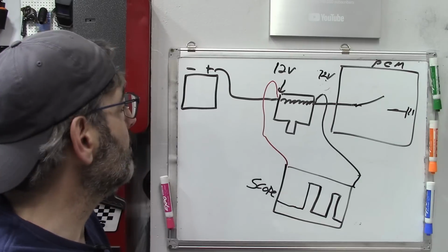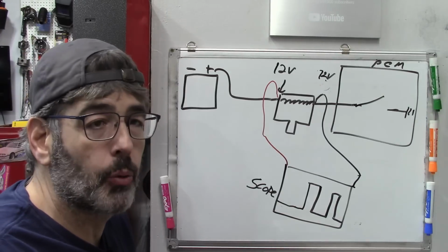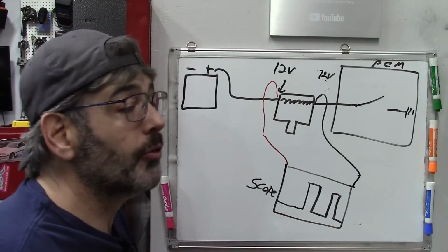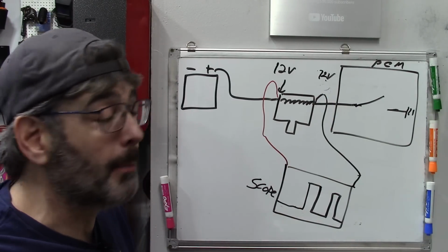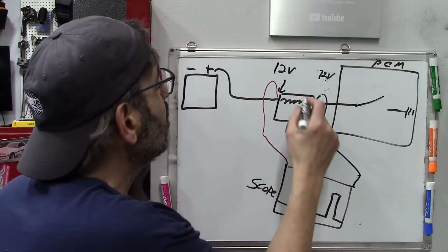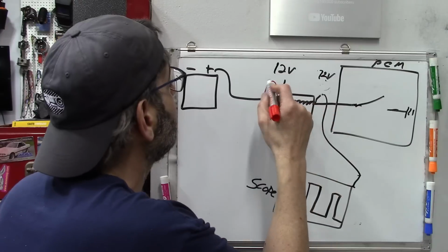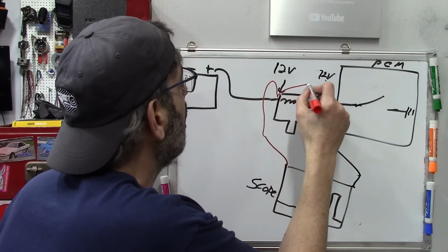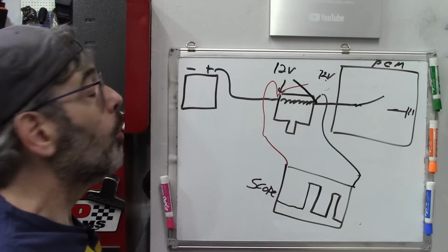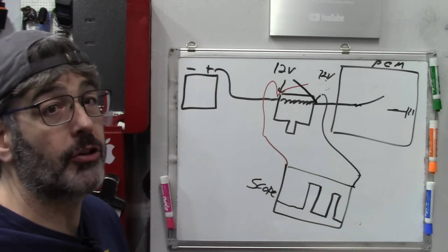Now, the reason this is important is because sometimes you run into things where it's very hard to access the connector. The other thing, it is very, very important to realize that if these are close together, and we cross our pins with our back probes up here, well, now we have basically destroyed the computer.